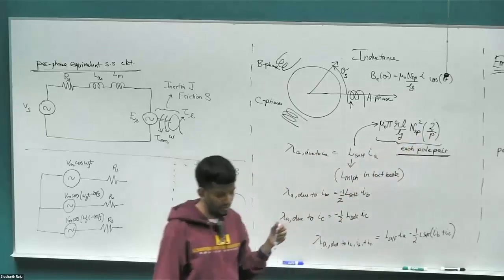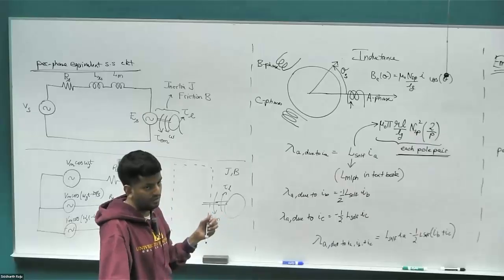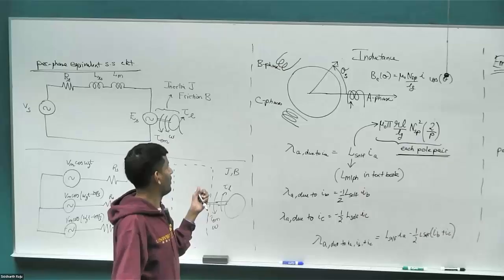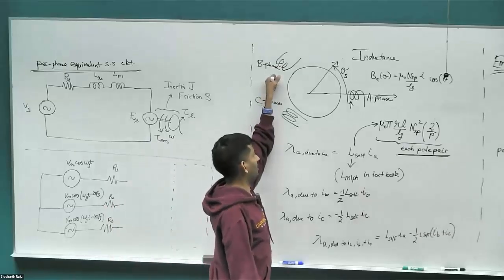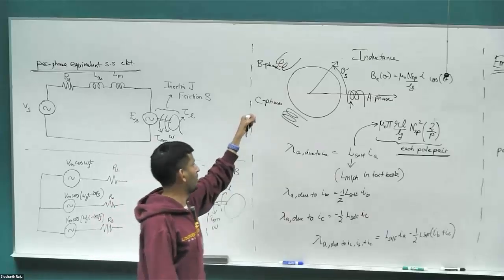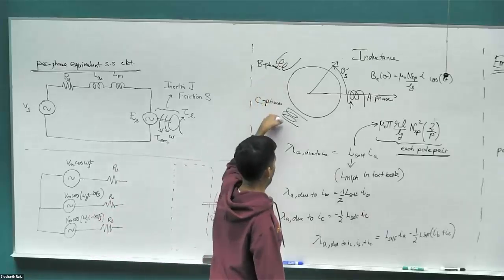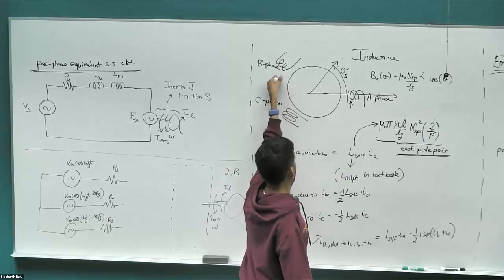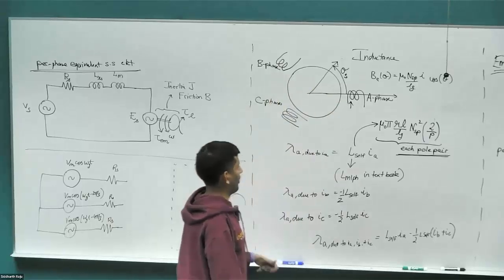Then we looked at the second way of deriving the same thing using the method of flux linkage, which is far more powerful because the energy equation doesn't tell you anything about what happens when the other coil carries current, what will be the effect on this primary coil. It complicates the picture a little bit. You can again find the B field due to this, find the energy, but it will be hard to decompose the energy of itself versus the energy it's contributing to the other coil.